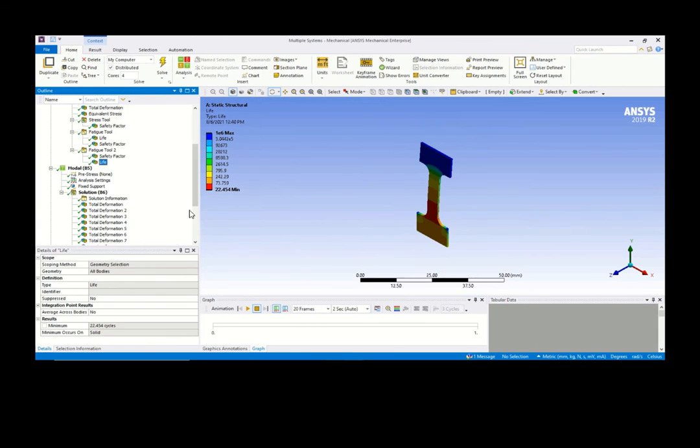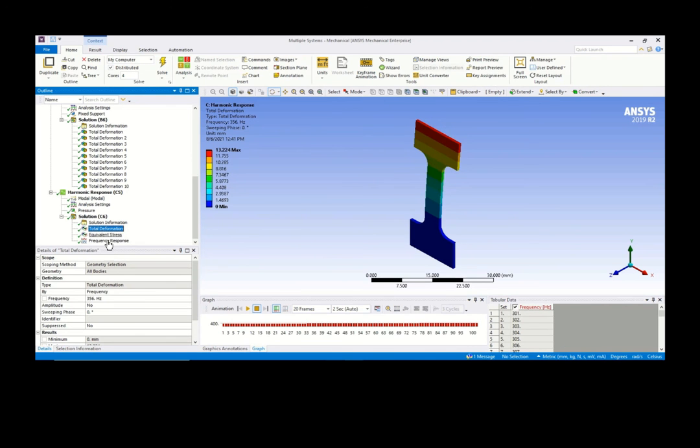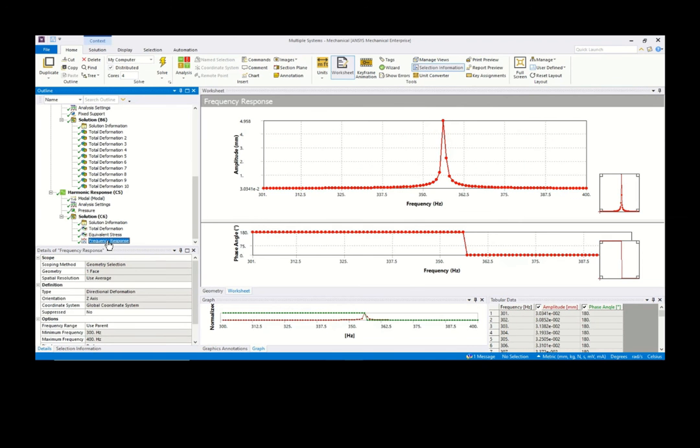Let's say I'm not going to excite this thing at very high frequency, maybe just 100 hertz, which probably has no issues, or maybe just 10 hertz. Okay, I've just run at 10 hertz, excitation frequency 10 hertz. The force is still the same, the amplitude the same, still 500 pascal. But the maximum frequency that I can go to is just 10 hertz.